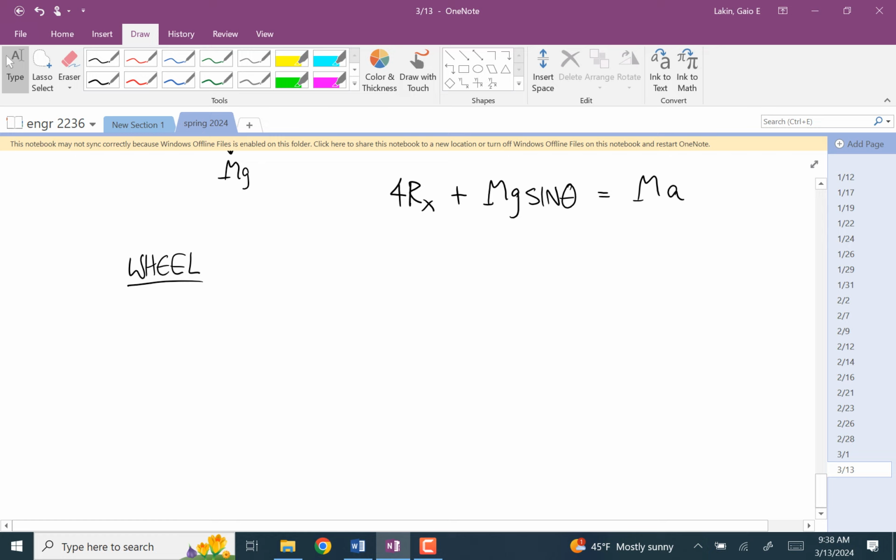Is there a fixed point on the wheel as it rolls down? There's a point fixed to the body, but not fixed in the coordinate system. And there's the point in contact with the ground that has zero velocity, but it doesn't have zero acceleration. So no, there's no fixed point. And so the about point is the center of mass of the wheel.